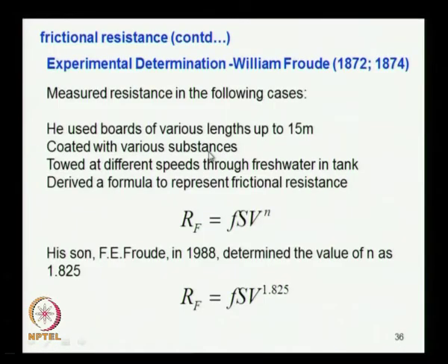He used boards of various lengths, up to 15 meters, coated with various substances. We have seen that depending on the surface there will be a change in the resistance. They were towed at different speeds through fresh water, as I have already explained. The total frictional resistance R is proportional to the surface area and also to velocity to the power n. F is taken as a constant.